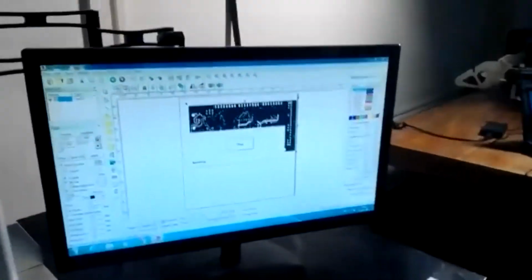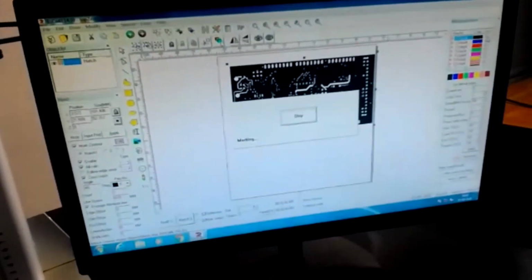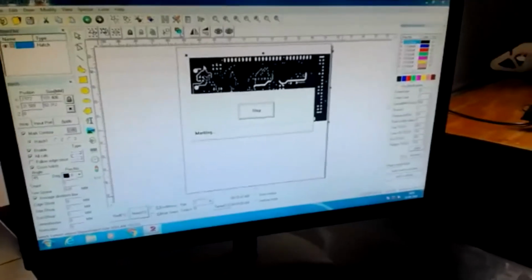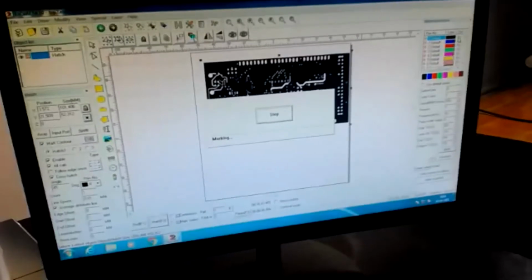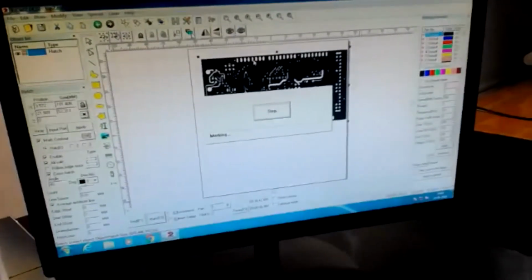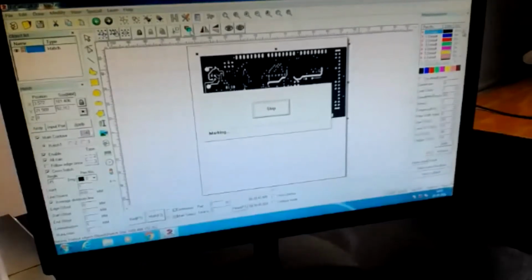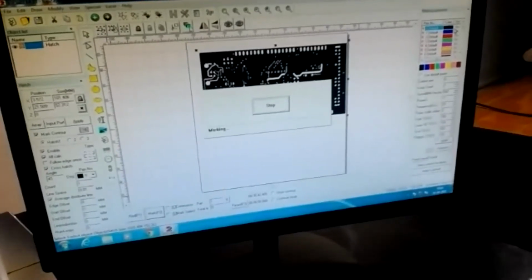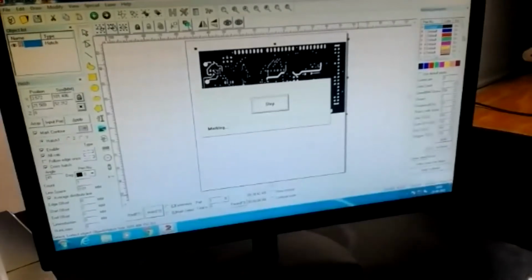So here, the very important thing when you do this etching process is the color code you choose, and keep the color code on. For example, in this diagram I'm making black the engraving area. So the black is the pen I keep on, and the white is the non-engraved area. I don't want to engrave it, so I keep white off, and I don't need to do anything for white. I kept black on, so the black area will be engraved. The other areas will not be engraved, so that you get the desired pattern in this circuit.